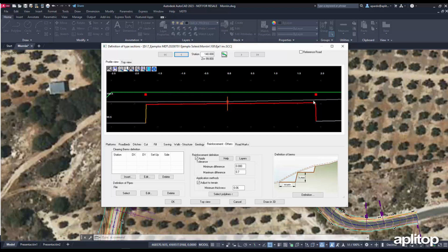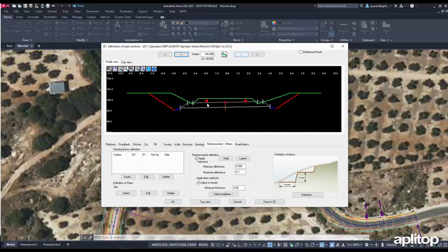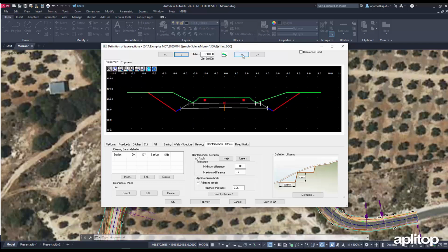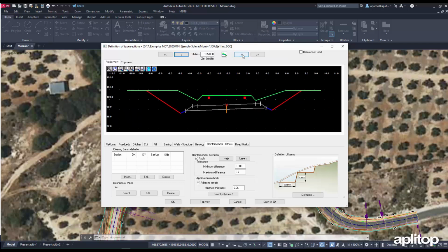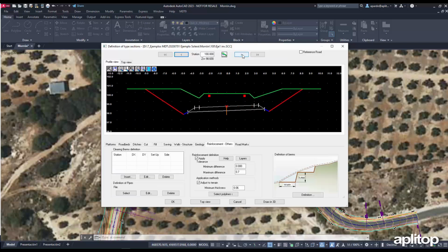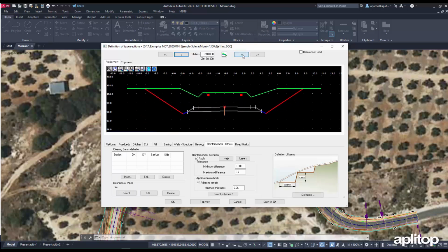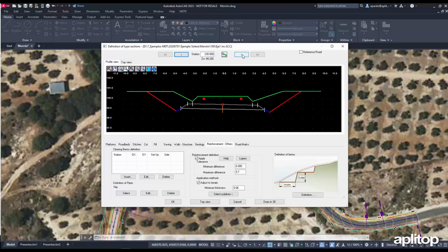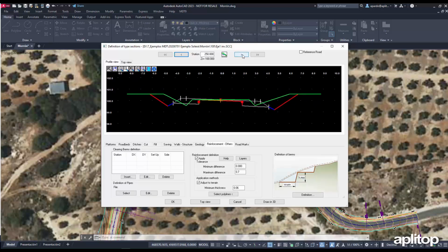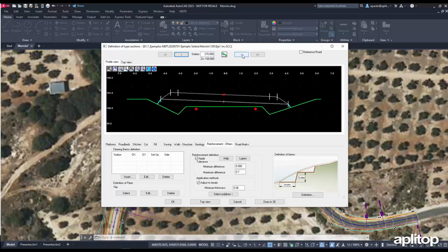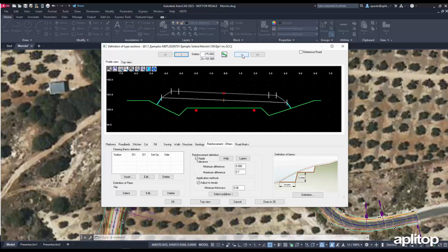At the next station, 145, reinforcement is no longer applied since the distance between the natural terrain and the subbase is greater than the 0.7 meters indicated in the maximum tolerance. A cut section where it is already necessary to remove the entire template. And so on throughout the road. The reinforcement is applied in the area of action marked by the two polylines. It is on tolerance and it is within roadbed both on embankment and cut area, adapting to the terrain or final platform while preserving a minimum thickness if necessary.